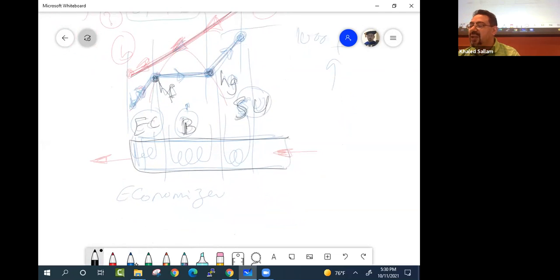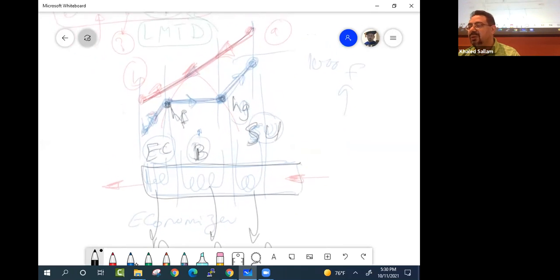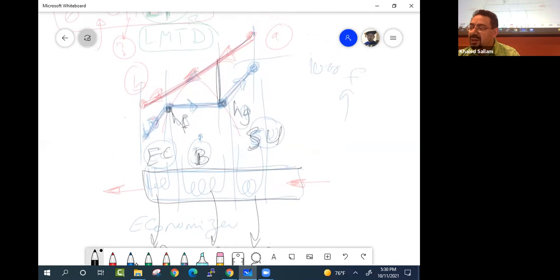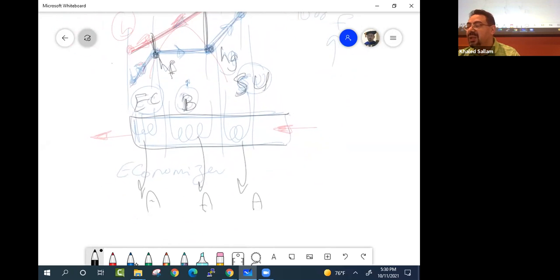And so the project is asking for this area, this area, this area, for each part of the coil. For each part, we need to know what the delta T is for that part so that we can use the one and only equation in heat transfer, which says Q is UA delta T. Of course, the U is a big question.